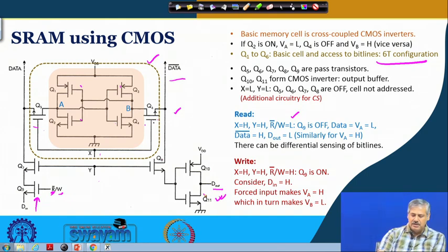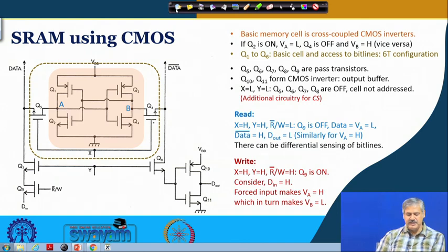Right. Now, how does the write operation take place? Again, these two address lines should be high. Okay. Chip select, which provides access to this particular chip, should be at a proper value. Okay. Now, this is 1. So, D in is allowed to enter, right, and when this D in comes here, again this is a forced input, for which this particular output will be of a high value.